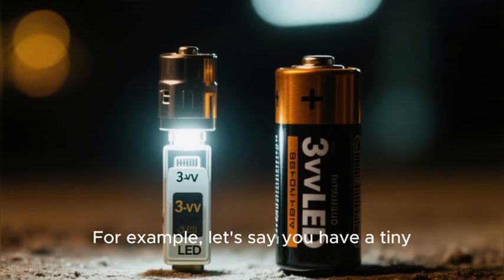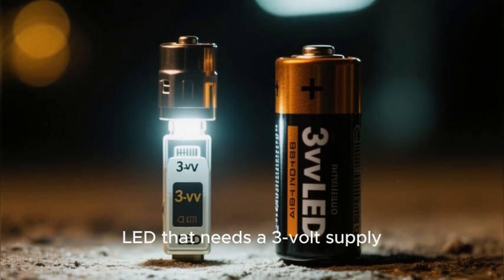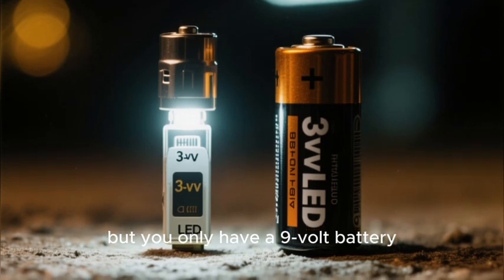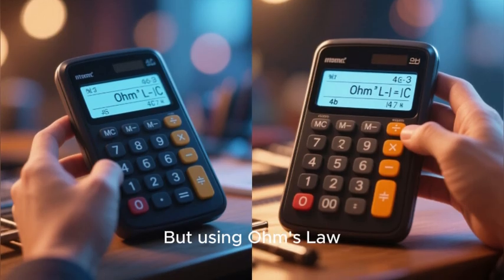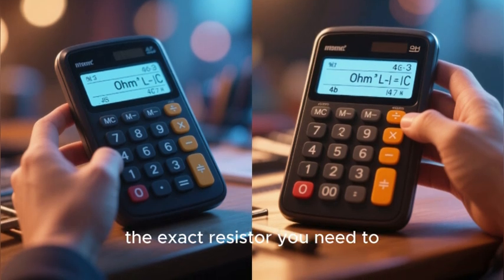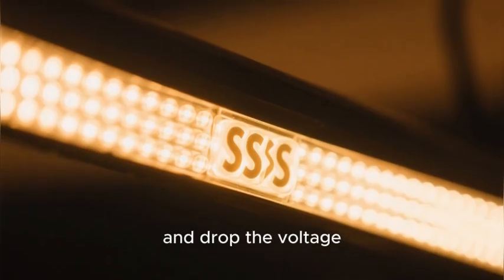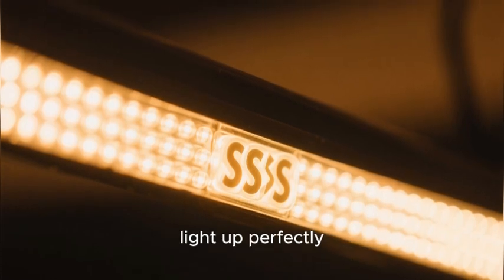For example, let's say you have a tiny LED that needs a 3-volt supply, but you only have a 9-volt battery. If you connect it directly, pop, the LED is gone. It can't handle that much voltage. But using Ohm's law, you can calculate the exact resistor you need to add to the circuit to limit the current and drop the voltage, protecting your LED and making it light up perfectly.